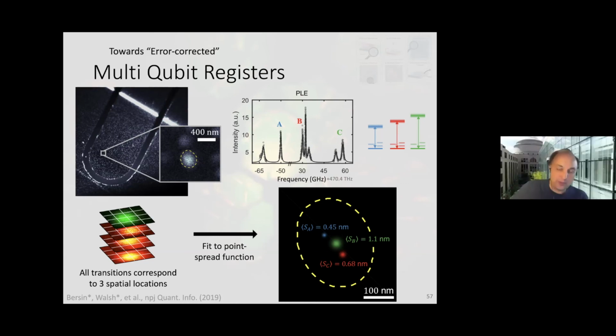You know, when you mentioned silicon, I just realized that last week, or 2 weeks ago, we installed in MIT.nano the new focused ion beam SEM system. And one of the sources is indeed silicon, capable of producing 8 nanometer accuracy in positioning. Typically used for milling, but I imagine you might be able to use it for implantation just the same.